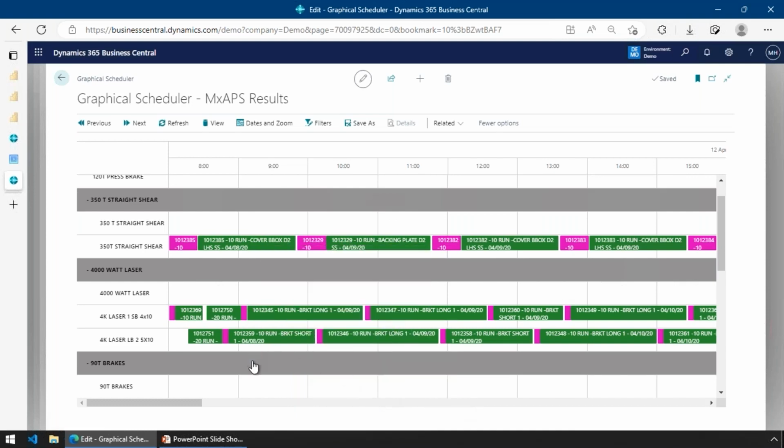And again, we can eliminate that setup time if we've got that set up. If I'm running the same part multiple times or similar parts, I can do a partial setup reduction or a complete setup reduction. So for example, if I've got a die that I'm using or a mold is better. I've got a mold that I'm using and a different color.